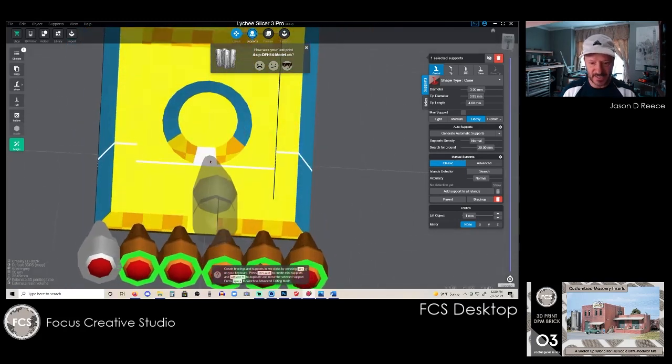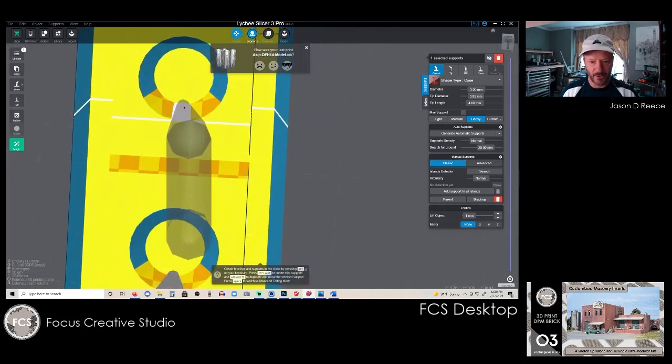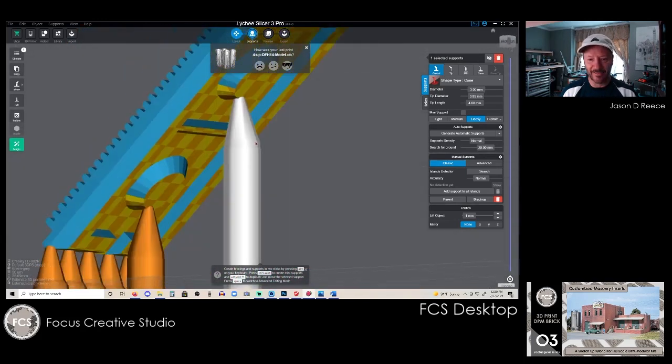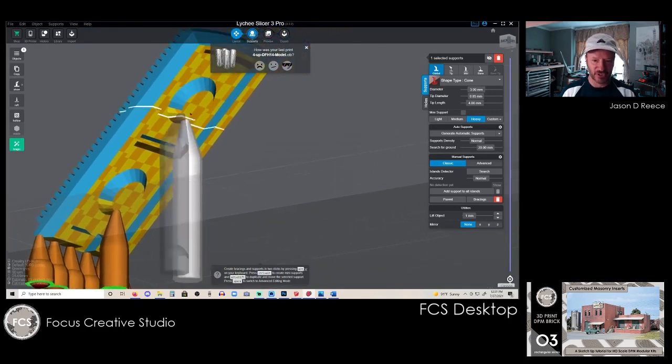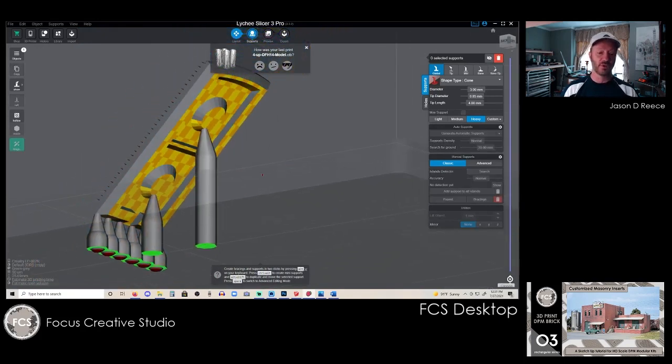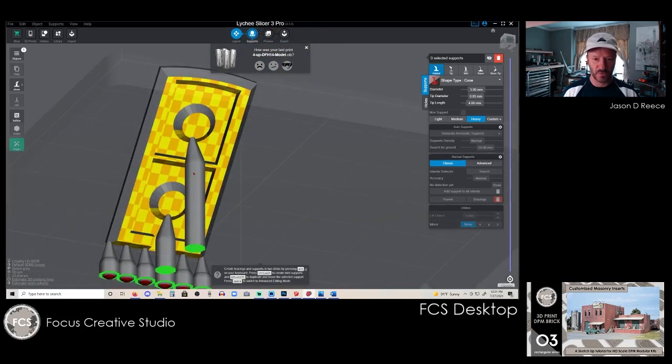I just hit this edge right here. 1, and that one right there. It's not an island, but it's out at the outside edge, so resin's going to print. The resin is printing basically where that white is, so it's going to print all the way at the edge. I anchor that outside edge, which is the main point of this. Now I'm done with heavies. There's no other heavies that need to be placed on these models.